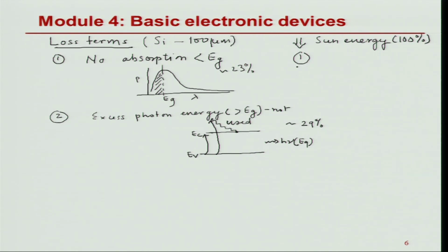So, you can see that from 1 to 2, because of the absorption and the spectrum the way we have, and we have a single material that we are using, we are almost losing 52% of light. So, you already come down to 52% in absorption only to the efficiency. Now comes the part that I will create electron hole pair and then I will collect them, and how the efficiency will go in that case.